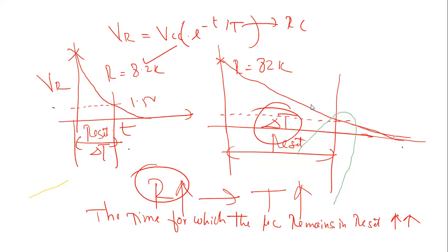Only two or more? Only two means you can only have two choices, either internal or external. Internal is the memory which is present inside the microcontroller. External means the memory connected outside the microcontroller. Outside the microcontroller, the memory size is limited by the number of address pins. In this case, it is 16 pins, which means you can connect a maximum of 64K. It is possible to extend this beyond that, but in a straightforward way, it is 64K. So these are the only two choices available.